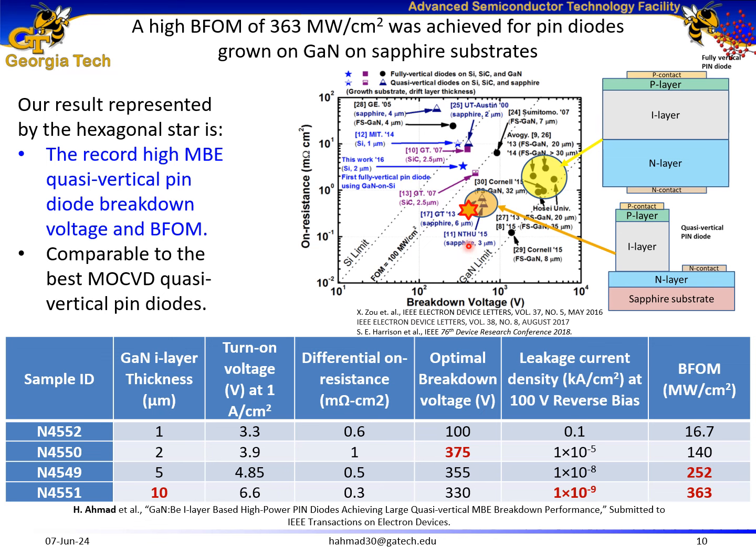And by comparison of our breakdown performance with the state-of-the-art quasi-vertical devices, we are comparable to the best MOCVD grown quasi-vertical devices, and we are the only group which are in the state-of-the-art MBE performance in terms of quasi-vertical devices. We achieved record breakdown performance and also record Baliga's figure of merit for MBE grown quasi-vertical devices.